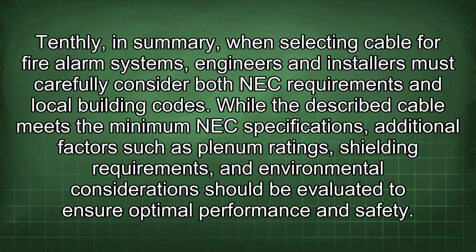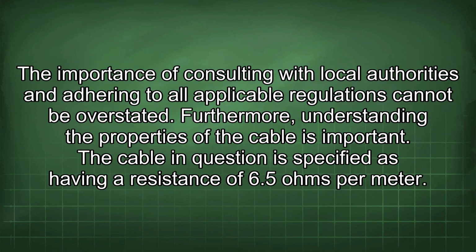Tenthly, in summary, when selecting cable for fire alarm systems, engineers and installers must carefully consider both NEC requirements and local building codes. While the described cable meets the minimum NEC specifications, additional factors such as plenum ratings, shielding requirements, and environmental considerations should be evaluated to ensure optimal performance and safety. The importance of consulting with local authorities and adhering to all applicable regulations cannot be overstated.